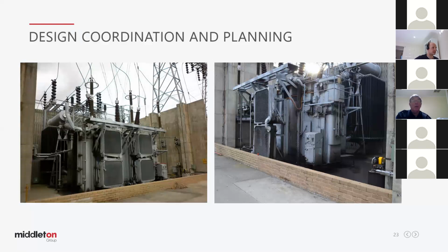Okay, so let's jump onto our primary design. So some considerations we might need to consider is the marshalling boxes for the transformers. So they might have a secondary marshalling box in, if it's a different transformer, where they're located, what type of, how many cables do we need from those marshalling boxes, what number of cables, are we going to use conduits? If so, what size conduits? We'll have to do some calculations around that. And it keeps some fill available, because there's no point, and it's very hard to pull off a conduit which is full of cables. You need to have some space availability there and some capacity in order to pull it. That comes down to an installation point.